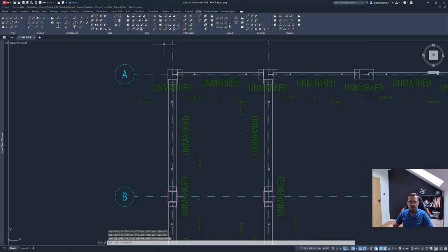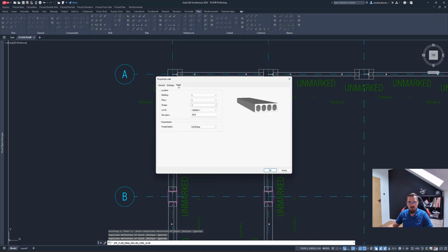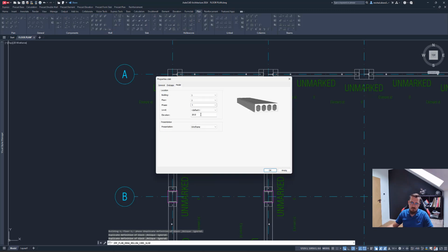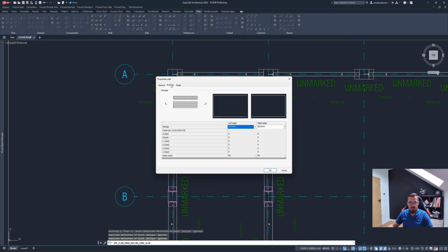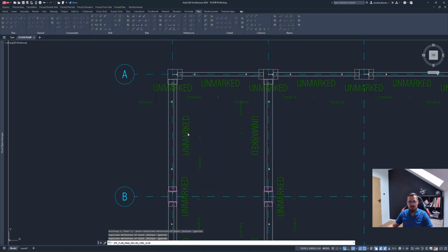Oops, let's go back actually, and then specify the height at which I want that hollow core. Okay. My math, will it be right? The height of that is 185. Okay, we might need to lower those hollow cores to sit flush on the beams. We'll do that after the fact, because we can still move the elements in the space after we're done. So let me just select that again and select the strands, and let's accept that.